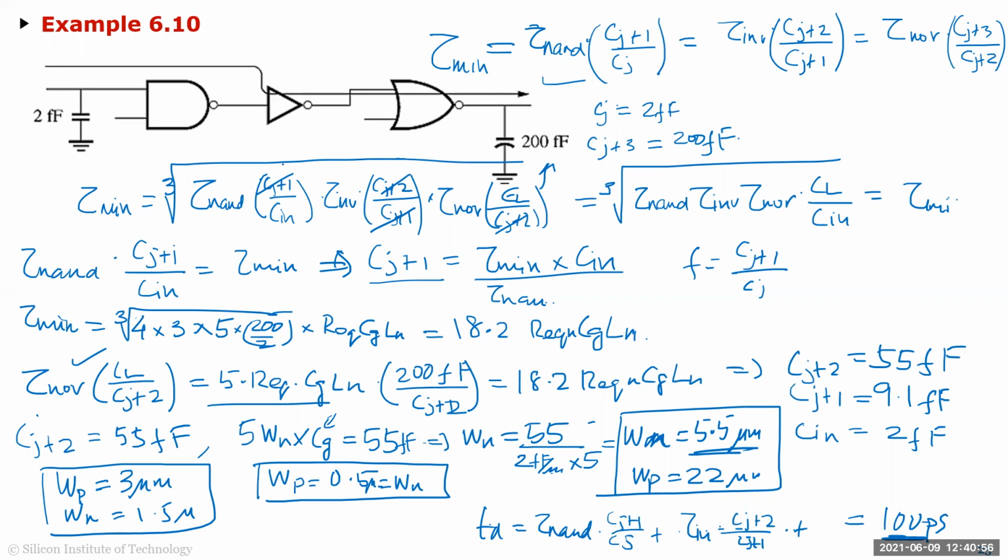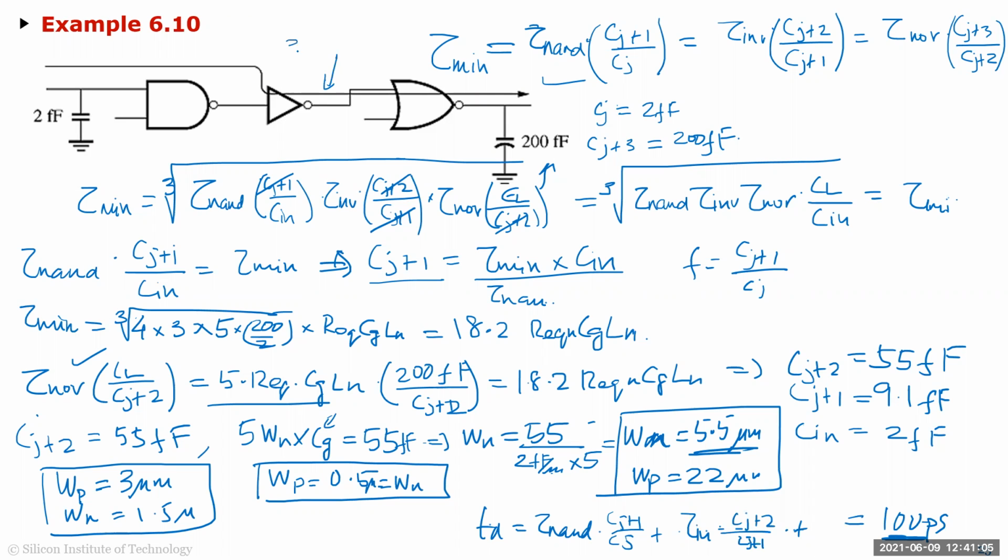Now, let's say you got a timing error and you get the critical path and this shows as like 300 picosecond. Then you know that, okay, there is some non-optimal path in it. So you can calculate this and say, okay, this inverter is not sized properly, or all three are not sized properly. So you can go in and size them.